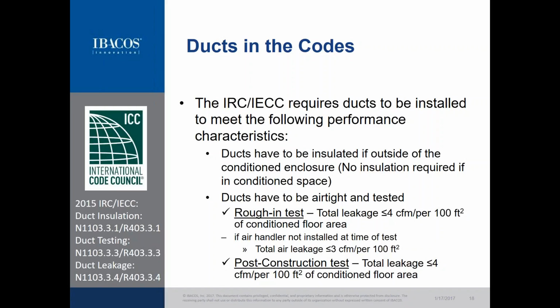When you talk about some of the performance requirements that are in the codes, and here looking at the IRC and the energy code, the IECC, we see that ducts are required to be insulated if they're outside of the conditioned space, the conditioned envelope. If they're inside the conditioned envelope, that requirement's not there. There are requirements in the code for duct air tightness and testing those ducts to measure the level of air tightness and ensure that the target levels are being achieved. Again, when ducts are located inside the conditioned envelope, some of those test requirements are no longer required.